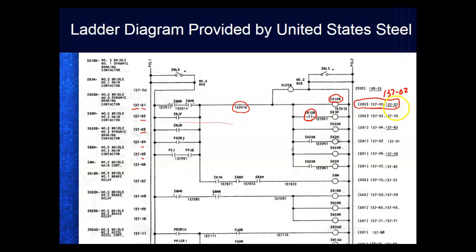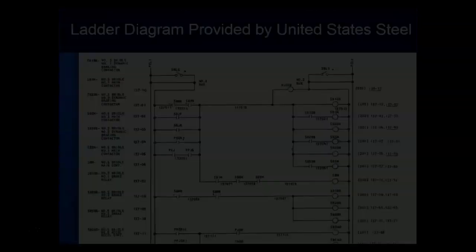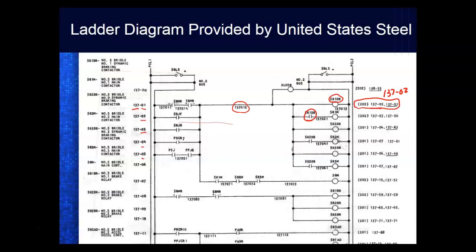It's underlined in line 57, but I don't have line 57 on my drawing, but I would know to go look for it, right? It says this relay's got a contact in line 7. So here's line 7, and what is that? Yeah, there it is right there.